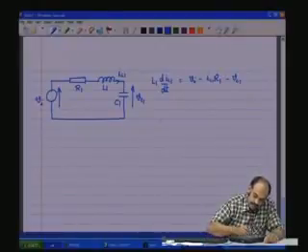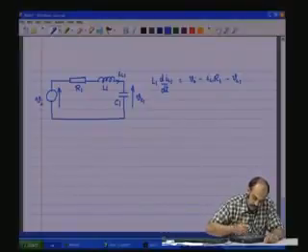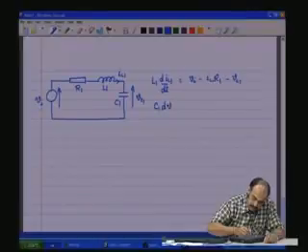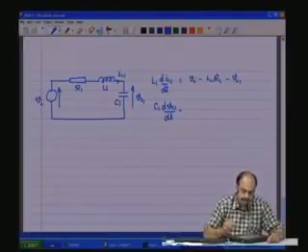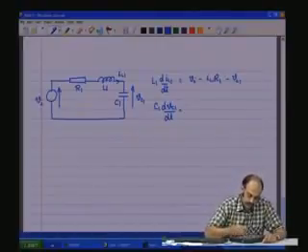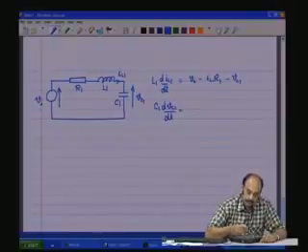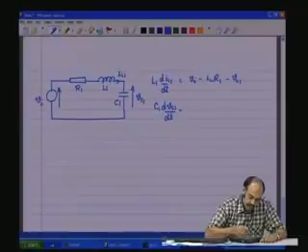You see that this is expressed only in terms of the state variables and the input variables, and C1 dVC1 by dt equals, we have done this in a previous session, I am just repeating this for clarity. So, the C dVC1 by dt is the current through the capacitance, which is IL1.